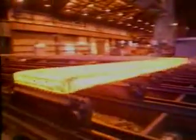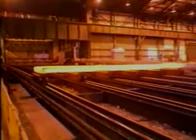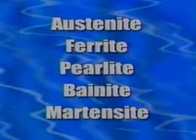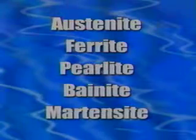Because of its superior physical and mechanical properties, steel is one of the most important materials in use today. Steel exists in various forms which are characterized by each type's unique crystalline structure called microstructure. These structures include austenite, ferrite, pearlite, bainite, and martensite. All of these possible microstructures can be formed by transformation during cooling from austenite.